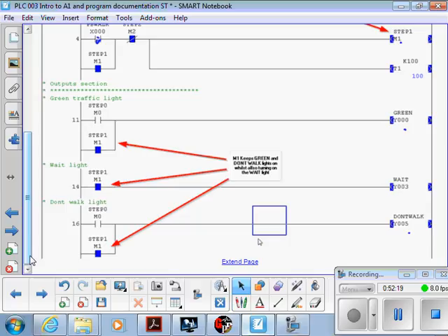And if you think about it, just this step sequence is going to be a copy of that line with some of the numbers changed to get the next piece of functionality to work, and add OR statements in the appropriate output line down the bottom so the lights work. Yeah? But the key thing that you're going to have to work out at the end is how do you get it to step from the last step back to step 0 again, when you want it to go back to the green traffic light and wait for someone to push the button again. So what makes it step back to step 0 is the key to finishing everything off.